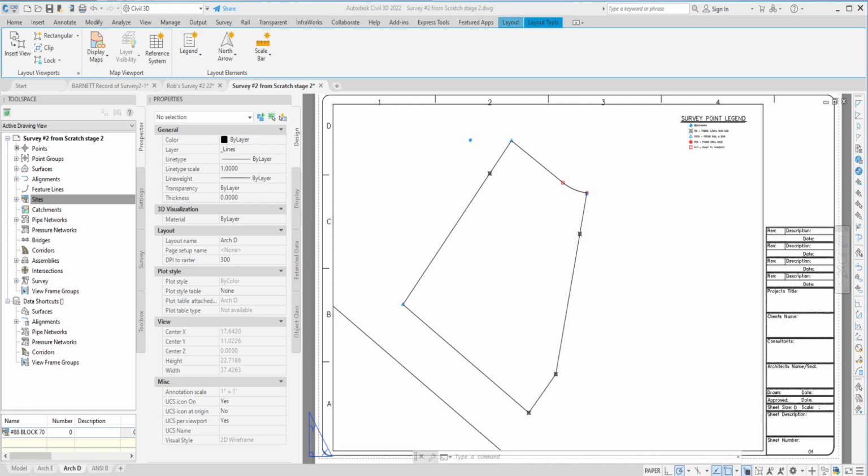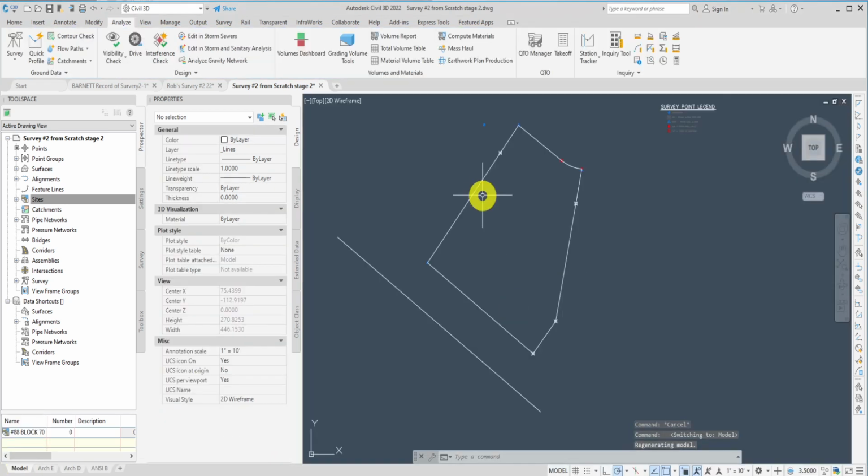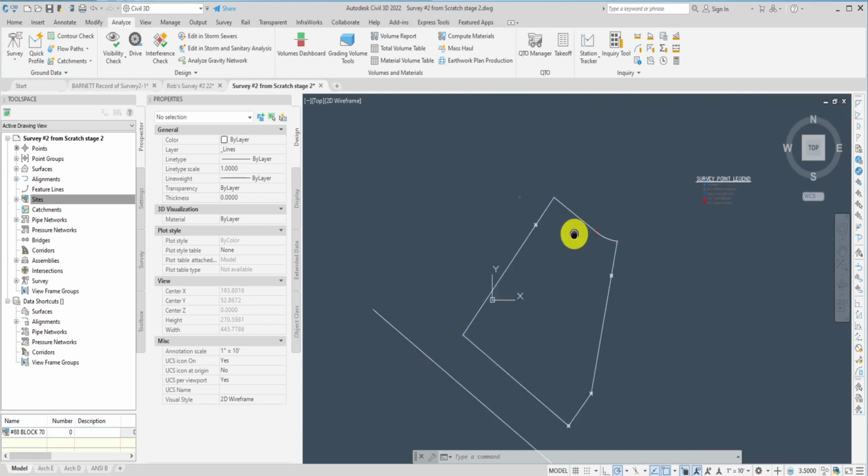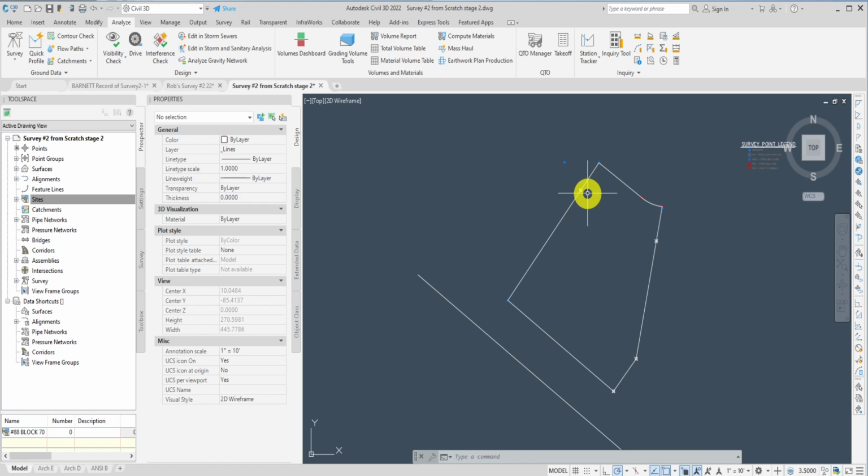Welcome everyone. I want to do a quick introduction, and we are in Civil 3D, and in a project early in our course we have drawn some line work. I will navigate to model space and show that we basically have some lines. We have created and set up COGO point styles, and these lines represent what will end up being a piece of land or a parcel. And this line will end up being an alignment, which is a center line of a road.